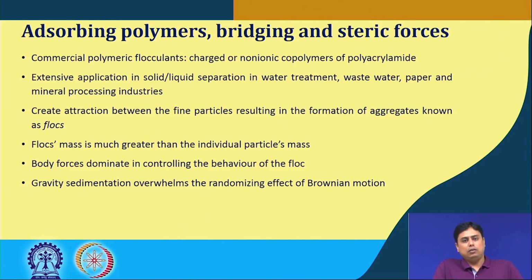Once these flocs are formed, as we have seen in the previous sections, they are bigger in size and of greater mass than the original fine particles. So, the body force then becomes dominant in controlling the behavior of these flocs, and it helps us separate them from the solution, like in gravity sedimentation. It overwhelms the randomizing effect of Brownian motion, so that they cannot diffuse further. We can have easy separation of these fine particles in terms of aggregates or flocs.